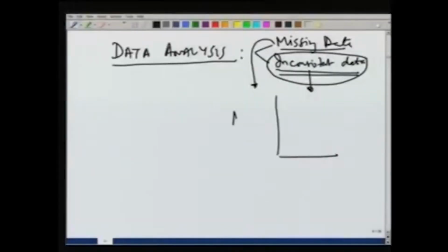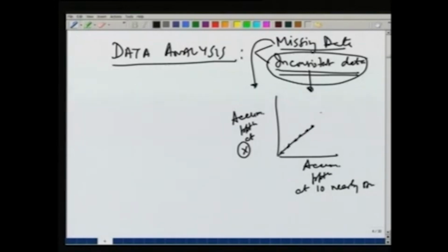accumulated precipitation at the station at which we want to find out whether the data is consistent or not, against the cumulative precipitation at a few, let us say 10, nearby stations, and ideally they should follow a straight line. If there is a variation from the straight line, that means the data is not consistent and we will have to modify the record. So, this is more recent data, this is the old data.